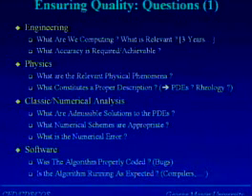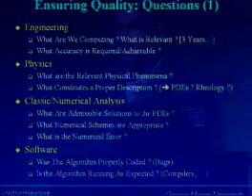As far as the physics are concerned, what are the relevant physical phenomena? What is it that I'm really looking after? And what constitutes a proper description? It's not just whether I'm solving Navier-Stokes, but whether I have the proper rheology. Is non-Newtonian flow really important for the blood flow that I'm doing? Is fluid structure really relevant? Am I just kidding myself, or do I really have to do this? So these are the types of questions that you want to answer there.